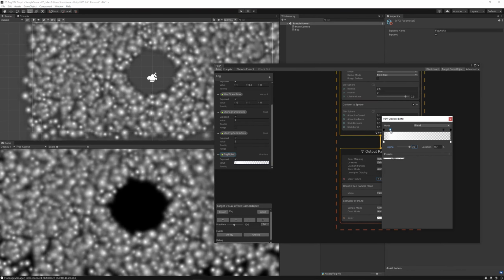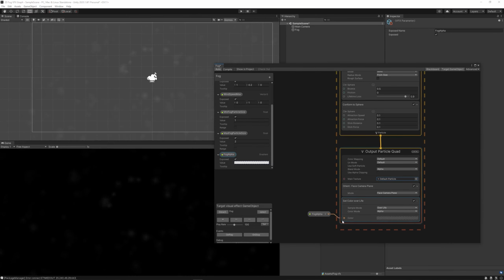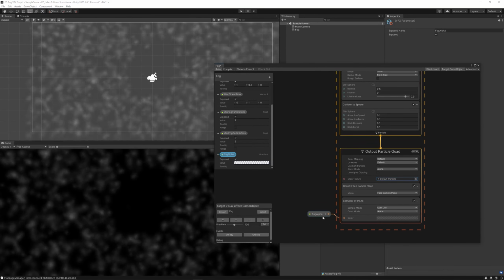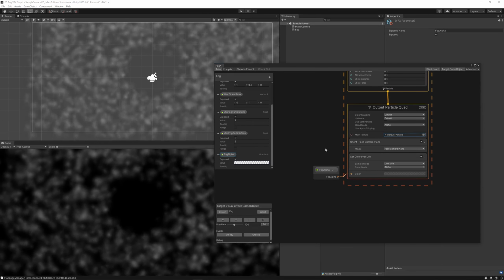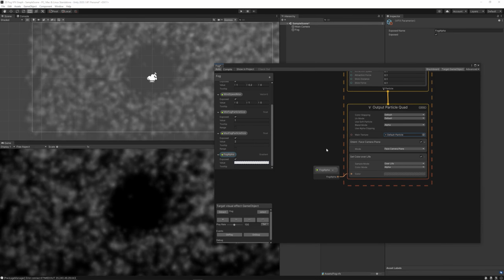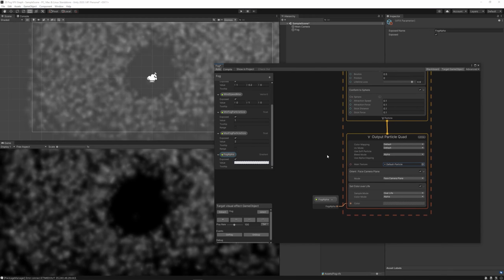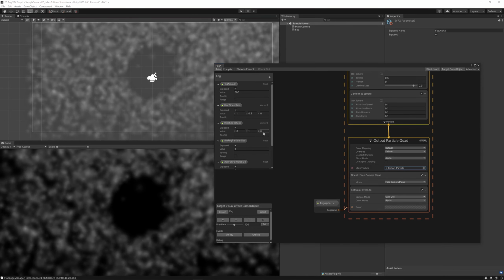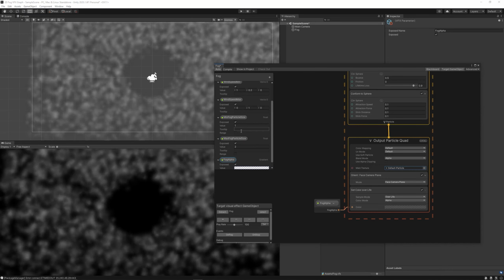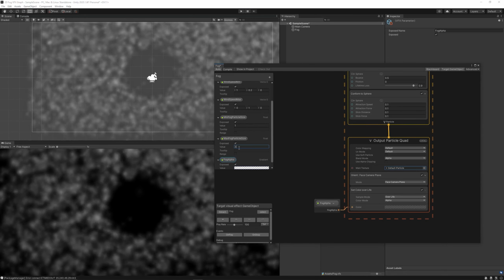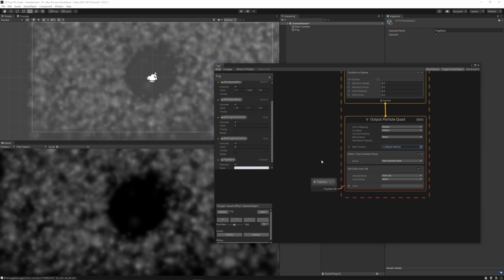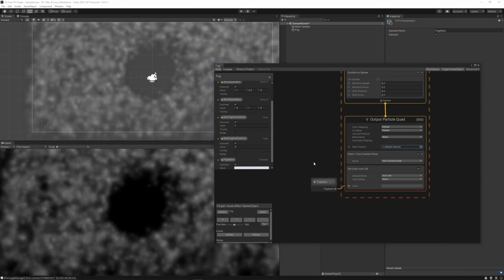Near the beginning and near the end, we can create 2 keyframes to control the alpha, and we can then control those. Maybe setting those frames before the end and after the start to 25 will give a reasonable, good looking alpha. Then link that fog alpha parameter to the color in the set color over life node. Also, I think if we increase the max fog particle size to 3, it will give a better result. Yeah, it makes it more realistic, I think.